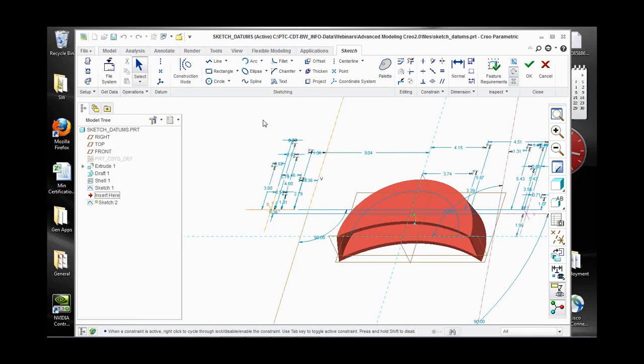Now, the one thing that you have to realize about this, which is very important, is that the only one that you can rotate around for revolves is that one. And nobody really tells you that. You can put this centerline in and try to revolve around it, but it just kind of stares at you when you get out of Sketcher and says, well, I still need a rotation axis. This is the only one that you can put in and rotate around at that point in time for revolves, okay? So these are geometry objects that you can reference outside of Sketcher. These are objects that stay inside the sketch and are just for construction only.